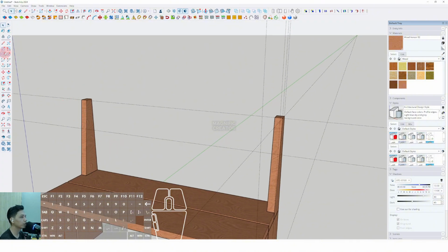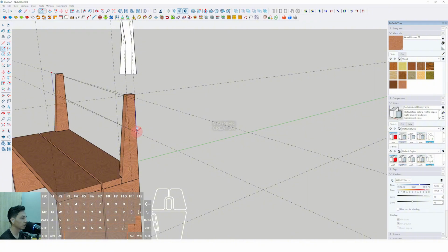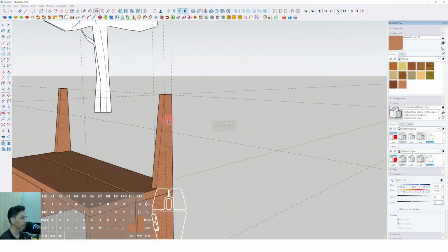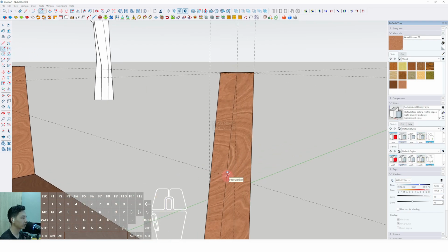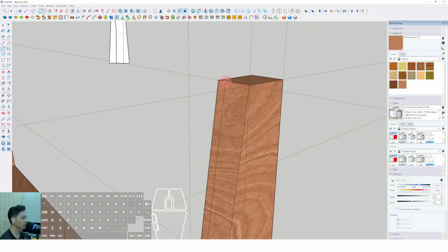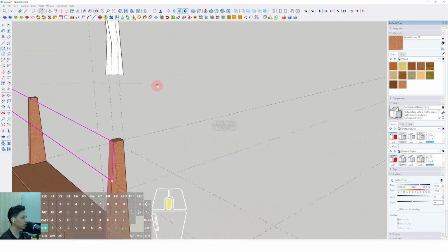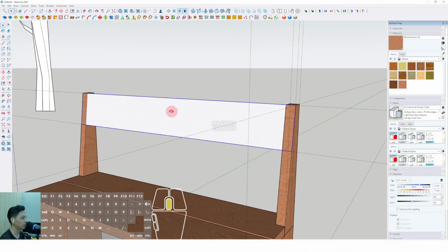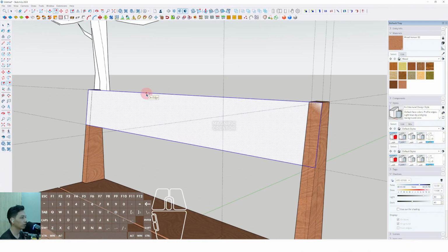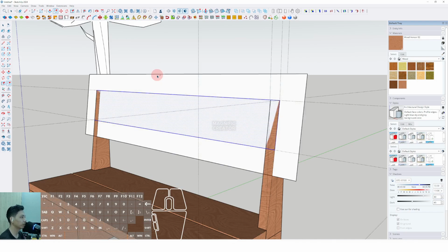Okay, now we can use the rectangle. I'm sorry, we have to click this surface, this rectangle, click this intersection and click to any side of this edge and drag to the position like this. Okay, then now we can triple click and select offset and click this edge and offset it outside around 100 millimeter. Enter.